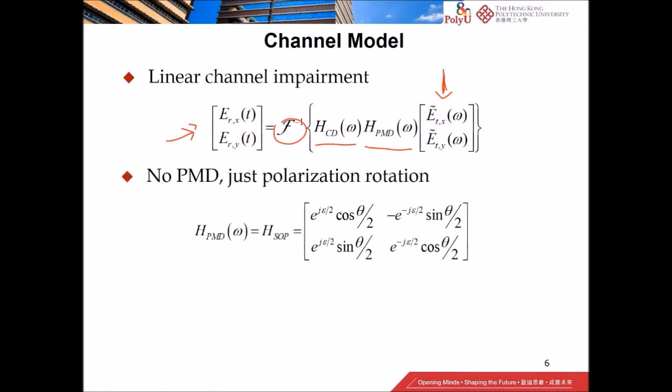Again, because of the length scale of short reach, there's also not much PMD, polarization mode dispersion. So in fact, when we talk about polarization effects for short reach systems, most of the time we are only talking about polarization rotations, between the transmitted signal and some components in between, and then the received signal polarization. So this is primarily what we will focus on.